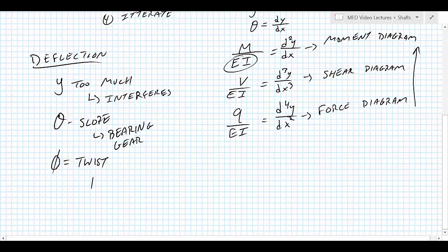If you imagine gears are not infinitely thin, even though we've pictured the forces as acting at a single point, if there's some torque acting on this shaft in the center, then there is some angle of twist occurring, and so there are maximum angles of twist that are going to be unacceptable to us as well.